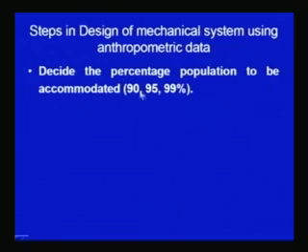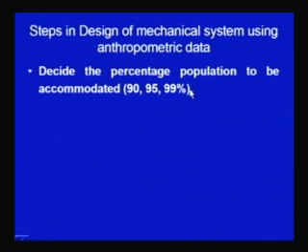It becomes uneconomical because, with a very narrow adjustable range of the features, most of the people are covered. For example, a 10 centimeter adjustable range can accommodate the 95 percentile people, while a 15 centimeter adjustable range may be required in a bicycle for the 99 percentile of the people, while 100 percentile coverage needs an adjustable range of 26 centimeter.